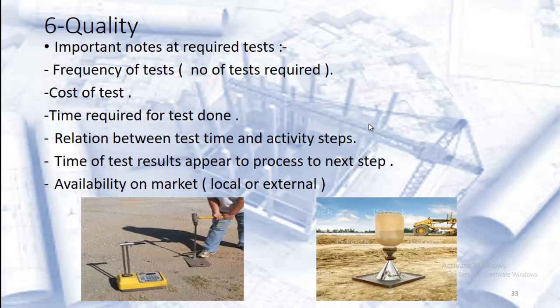Like we must do one pile loading test every 200 piles at bridges, one compaction test each 100 meters of length for roads, and others according to project standards and specifications. Cost of test, which is related to the time required for the test to be done.